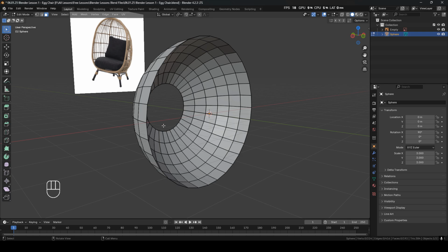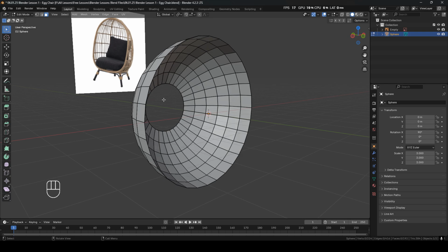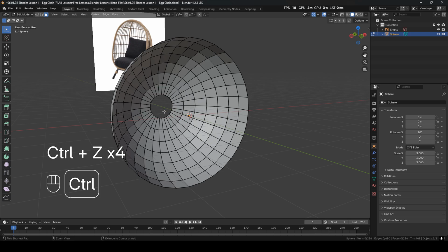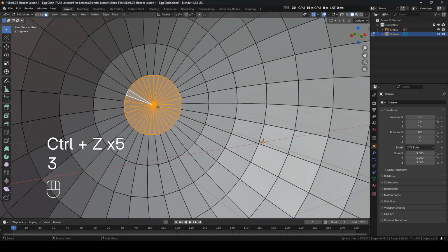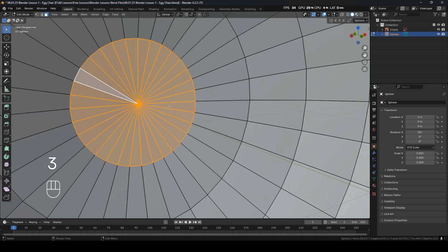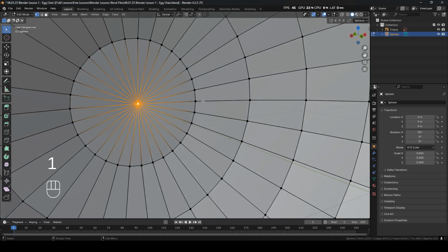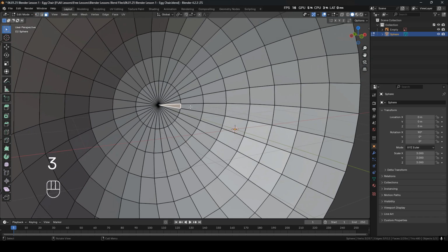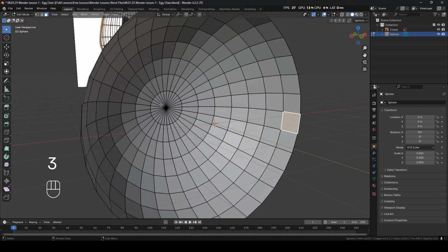I'm going to use the bag and I will do something different with that, because when pressing Ctrl Z, I don't like to work in tris. So these are tris, as you can see. There are 3 vertices it's connected to. It's always good to work in quads, always, and the quad flow is a big deal when you're modeling.